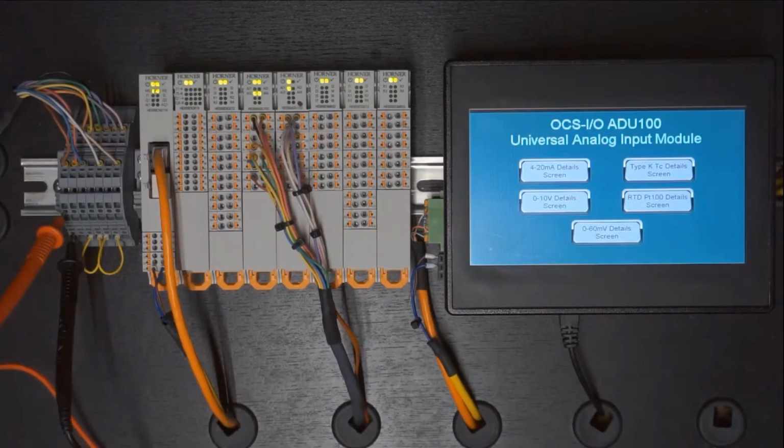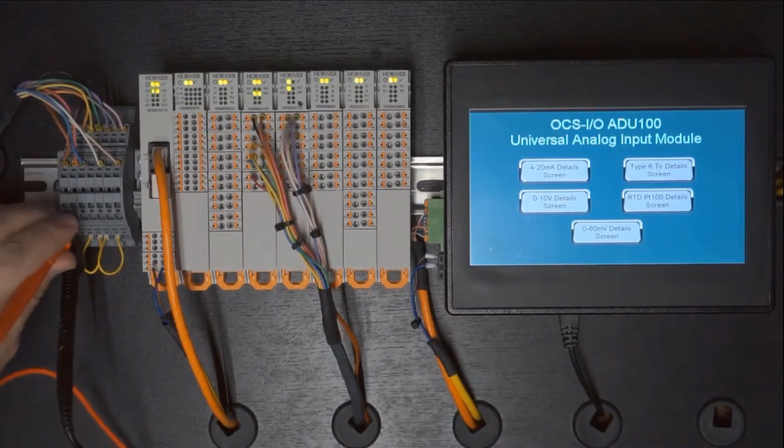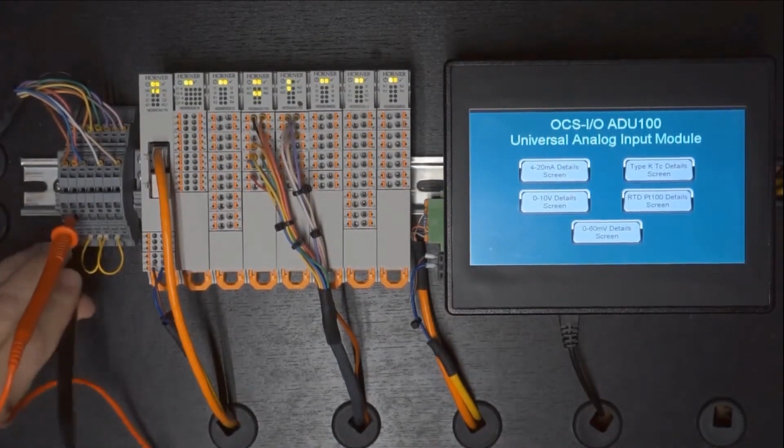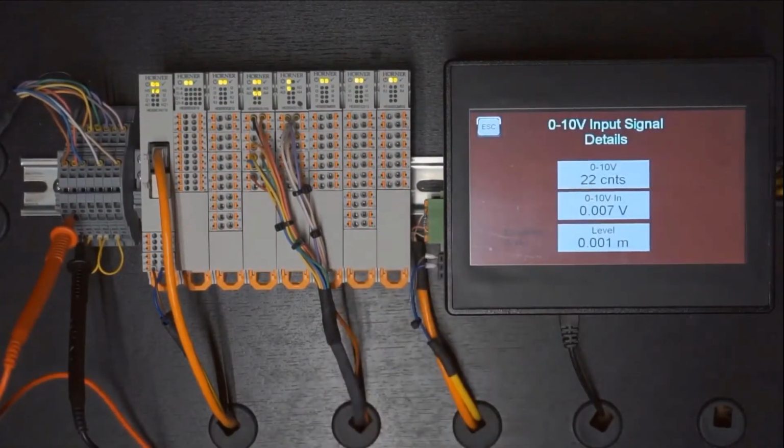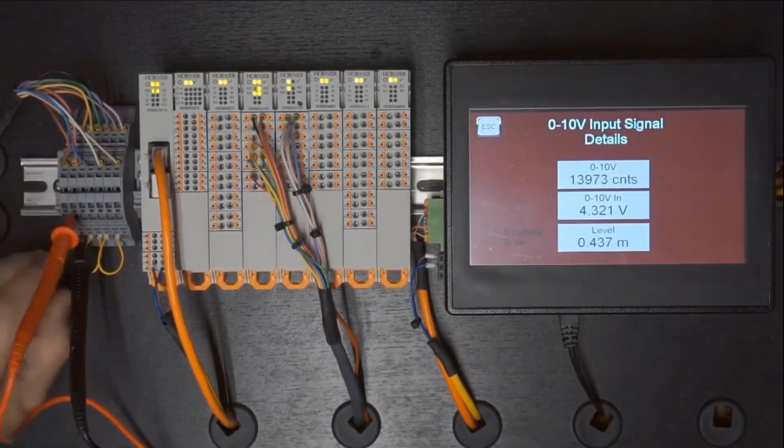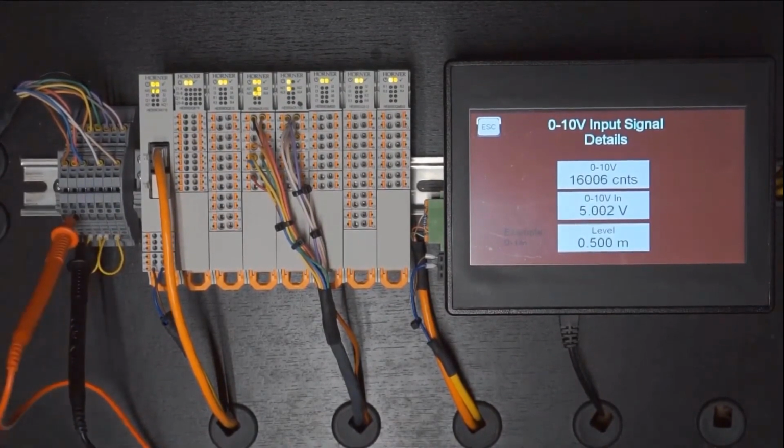So now we need to switch to voltage range to see how it works. To do this, we move the probes from the milliamp position to the voltage position. And then we need to move our output of the simulator to the next voltage channel. Then we change the simulator configuration from milliamp to voltage, and we'll go to, say, a mid-level range of 5 volts. And then we'll take a look here.